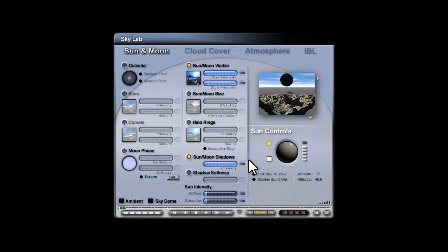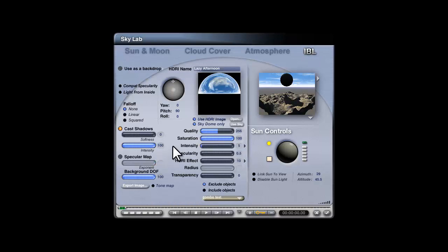Anyway, consider that you want to be at 100% intensity here, because if you want intensity control over the individual HDRI simulated light sources that are generated, then you have another control here to do that. For speed, and particularly if you've got a nice busy material on your terrain, then you can set the quality down, and we've also got the sun in here to provide direct lighting, so it's like it's a sunny day.